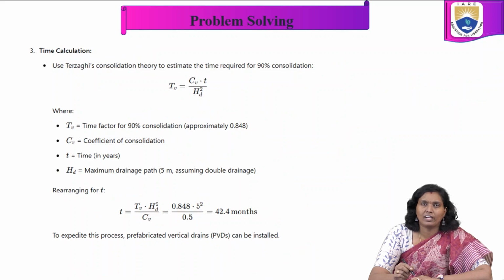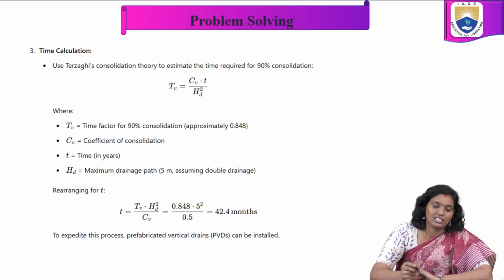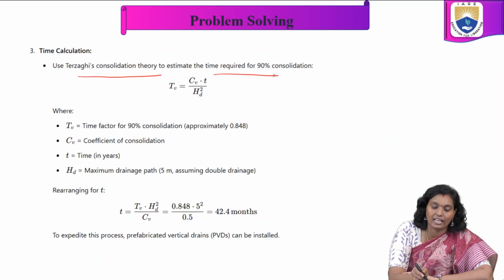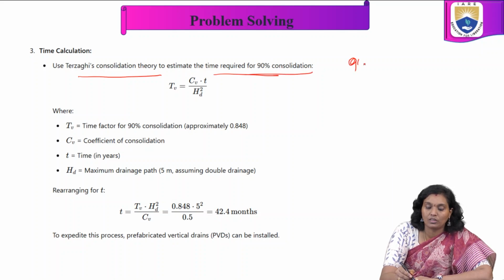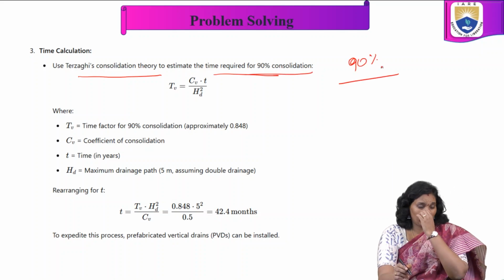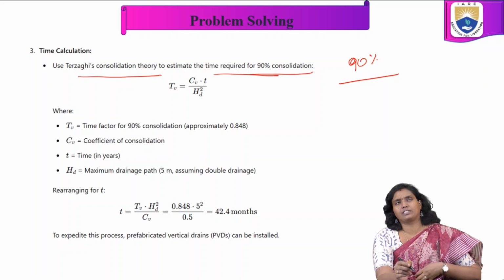Now we calculate the time using Terzaghi's consolidation theory to estimate the time required for 90% of the consolidation. 100% consolidation is difficult.